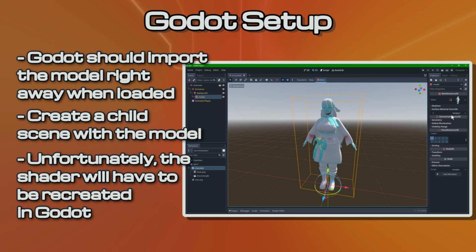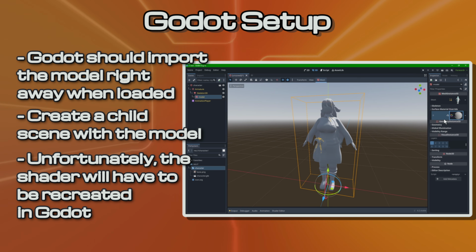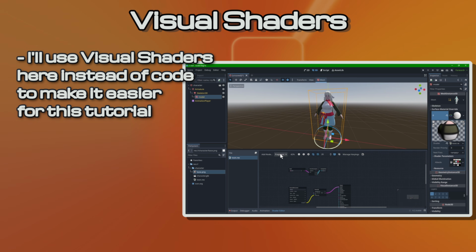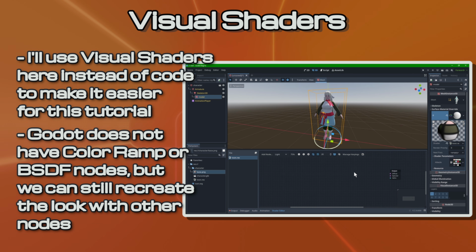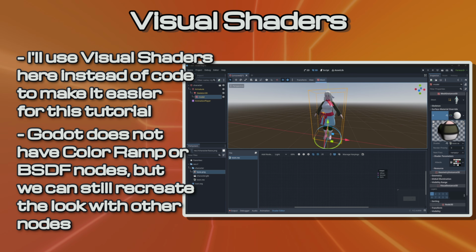Given Blender and Godot have different shading languages, the work we did to make the Toon shader cannot be exported from Blender. We will recreate the shader in Godot using the visual shaders, as that will be the most natural way to mimic the logic used in Blender. Godot lacks nodes such as the color ramp node, so we will use some alternative methods to solve that part. I'm not going to go too much in detail here on the shader, but I'll highlight the key differences